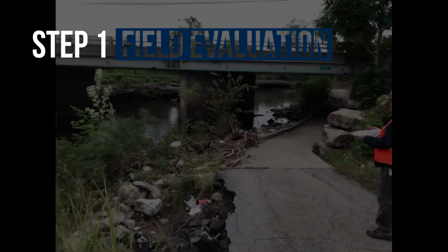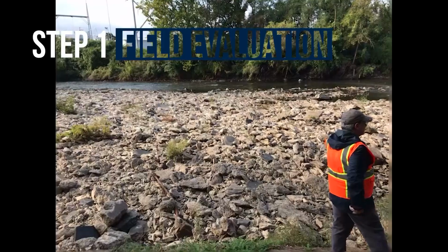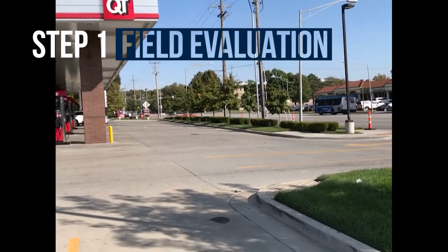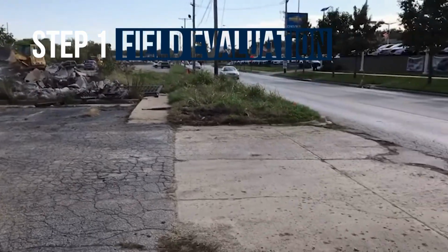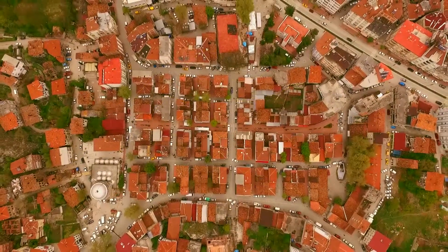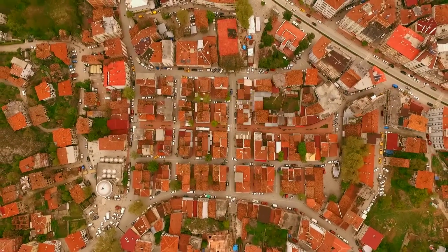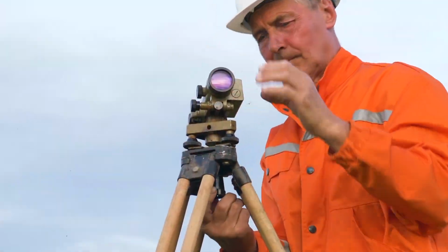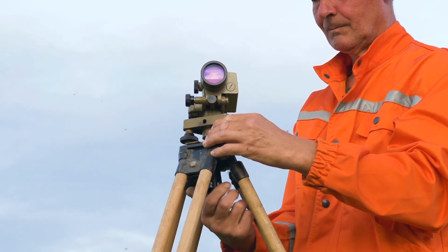The first one is really understanding the area that we're modeling, and so that includes some field evaluations, some site visits, actually walking the stream, collecting all the available data that we have, particularly all the mapping data. Fortunately, we're in a world now where LiDAR data is readily available to us, and it's good solid LiDAR data that's accurate. Of course, we need to supplement that with some physical topographic survey, and so we had surveyors actually go and do that, particularly for underwater shots, getting the bathymetry under the water so that we accurately depict the channel bed.